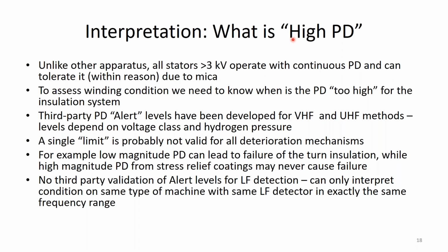And these tables, which we've only been able to determine for the VHF and UHF detection methods, have been independently third-party validated. Some of you might know Clyde Mon, a nice old gentleman, 94 years old now, who many years ago looked into our database, looked at the evidence, and independently validated. Other utilities have validated the databases. So we have been able to establish what we call alert levels. I try not to call it alarm levels, it's alert levels, because remember, just because you got high PD, it doesn't mean the machine's going to fail right now, okay?